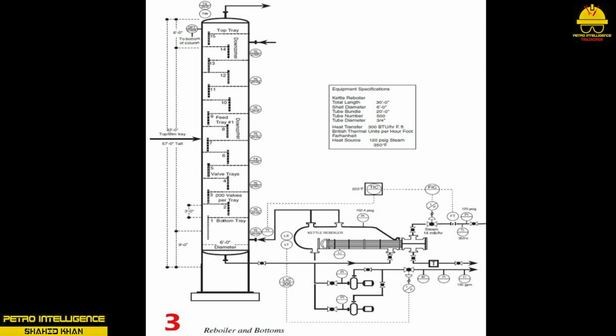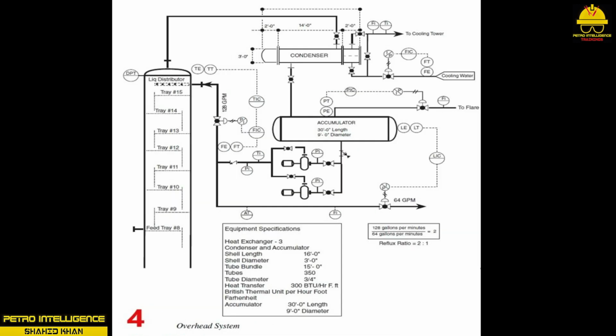The TIC is cascaded to the FIC. 14. Set kettle Reboiler FIC to required set point, auto. Put in CASC shortly after unit startup and feed is flowing. 15. Set unit pressure at required set point, auto. Monitor pressure during startup. 16. Line up reflux pump to column and off-spec, check suction and discharge. 17. Set overhead accumulator LIC to 50%, auto. Watch level increase during startup.